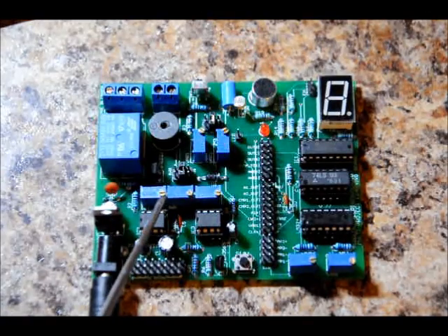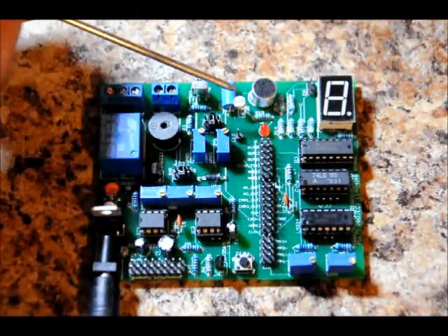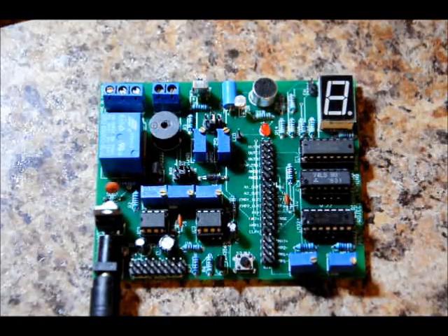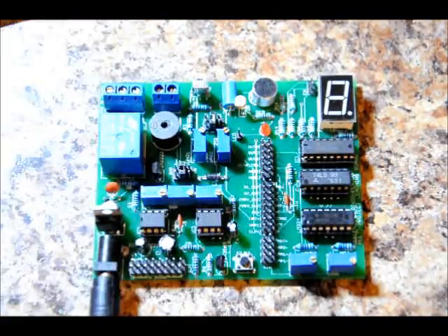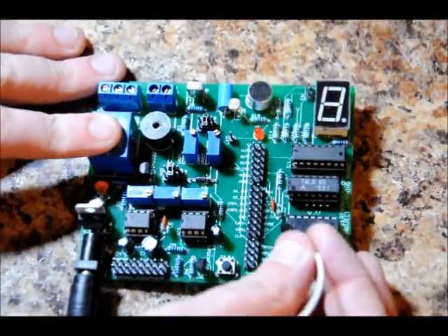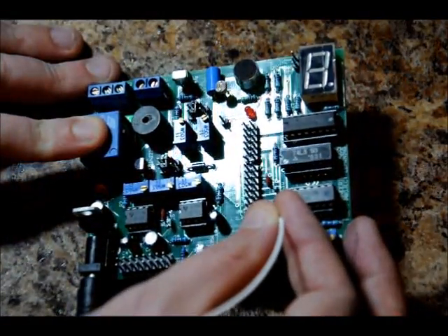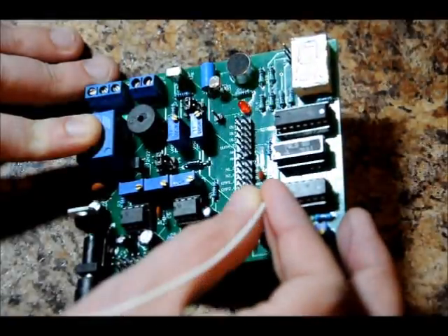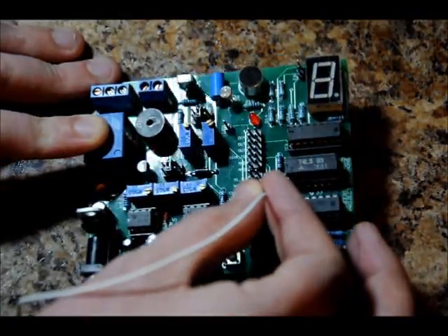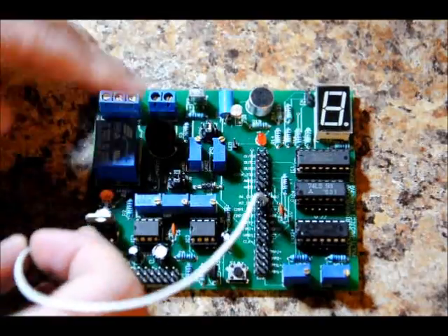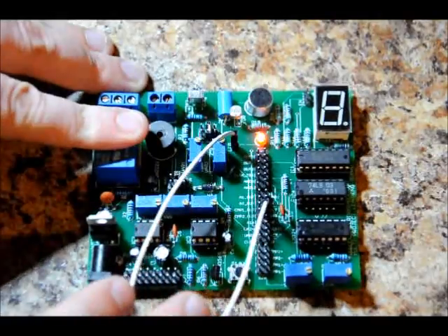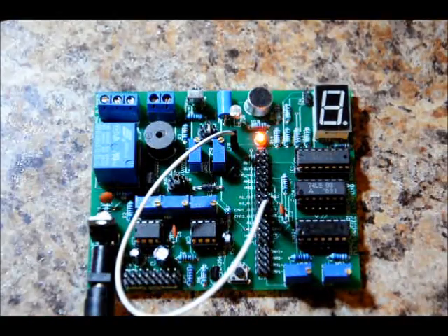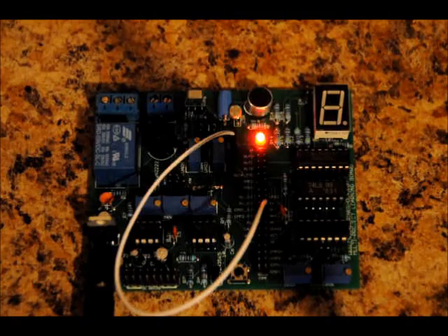So what we can do is adjust these 2 potentiometers to output a different frequency. But to see that frequency, we need to connect the output of the 555 timer to our LED. So first things first, I want to connect the Astable pin, which is right here on the board, to my LED pin, which is right here. So that's the pulse. Let me just turn off the light for a second. That's the pulse that it's creating right now.